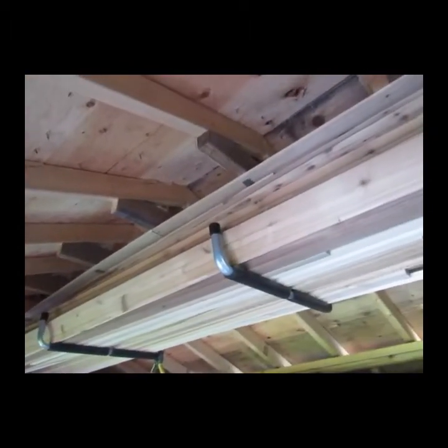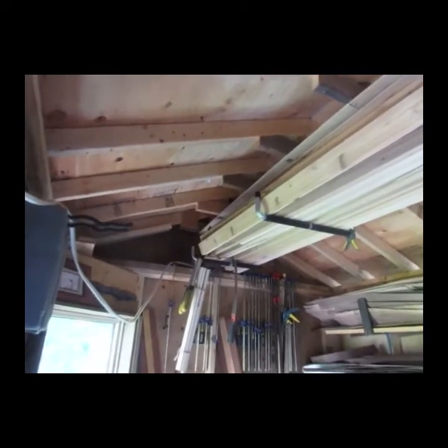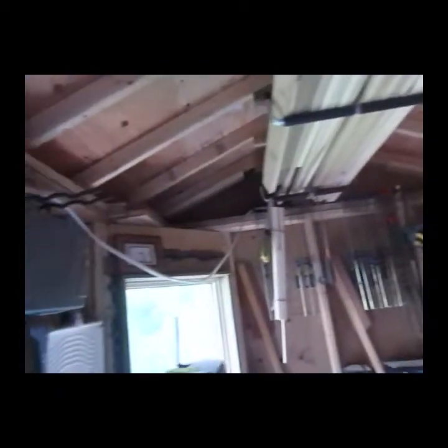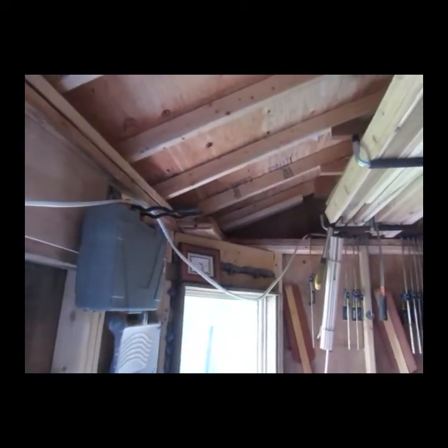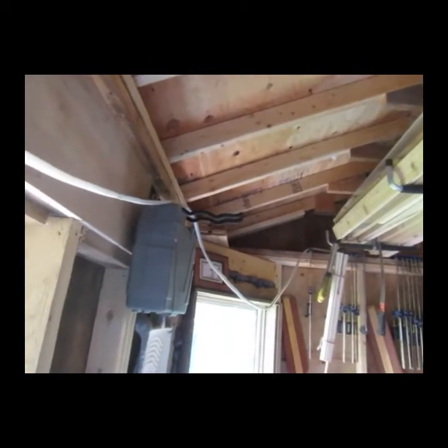I put them in place because I thought it would be fine to brace them from spreading to the left and the right. That is the purpose of a bottom rafter tie, which would tie the bottom third of those 2x4 rafters together. Now again, look to the bottom right and you'll see a picture and a little description of what a rafter tie is and its proper function.